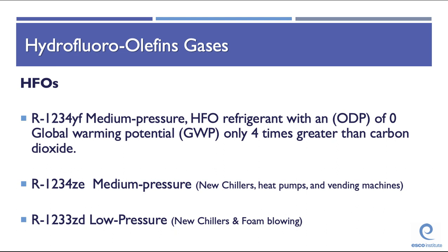R1234YF is a medium pressure HFO refrigerant with an ozone depletion potential of 0 and a global warming potential only 4 times higher than carbon dioxide. R1234ZE is a medium pressure refrigerant used in new chillers, heat pumps, and vending machines. R1233ZD is a low pressure version of the hydrofluoro-olefin gases used in new chillers and foam blowing.